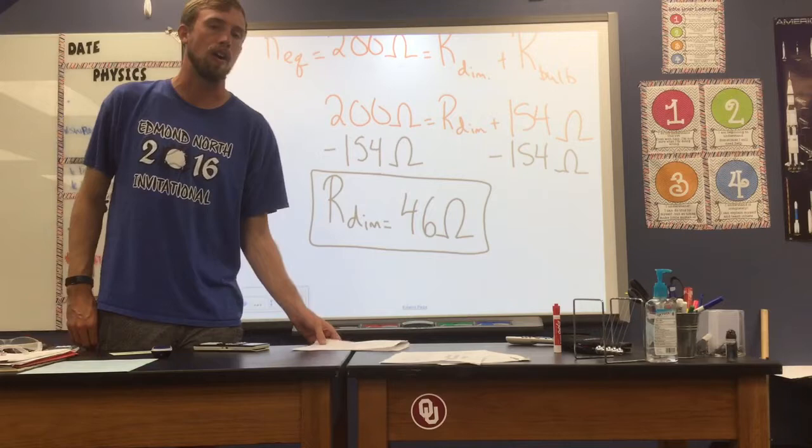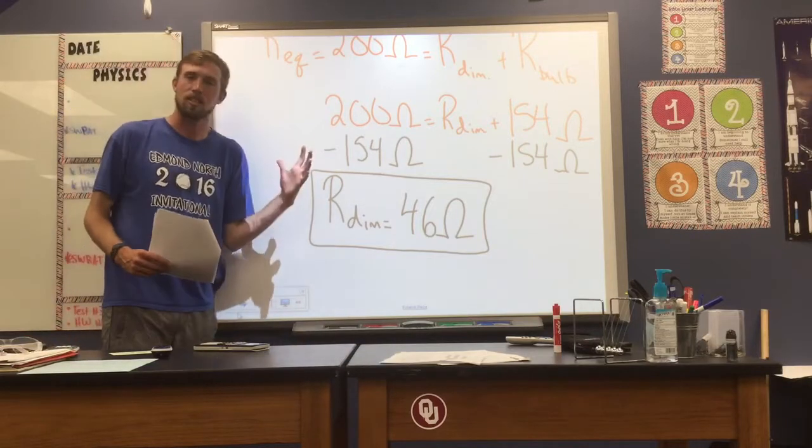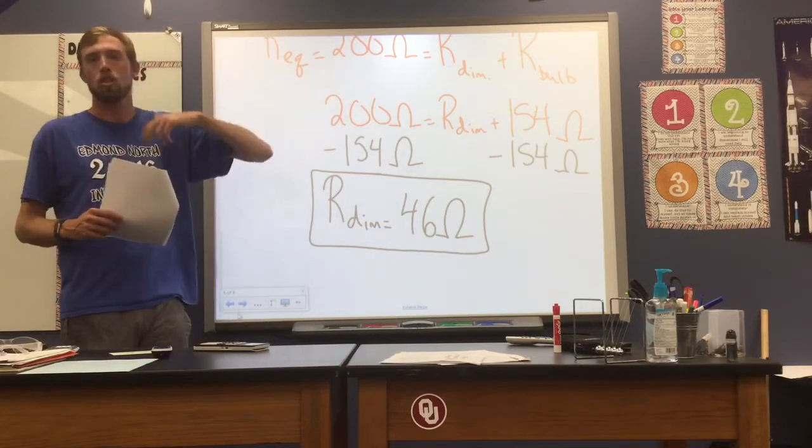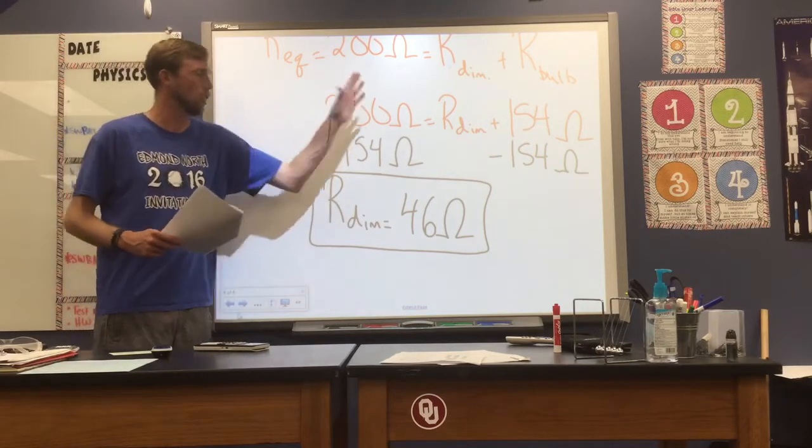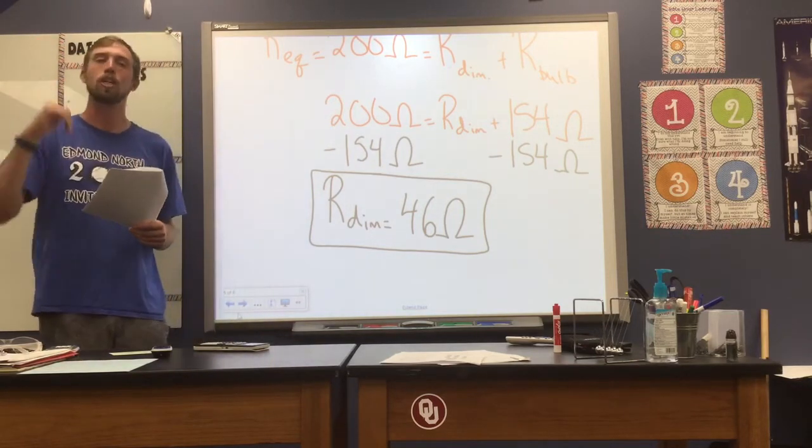So here, it's a matter of understanding equivalent resistance is the sum of two resistors that are in series, and how to use our power equation and Ohm's law. Hopefully this will get you started on solving questions 20 through 22.